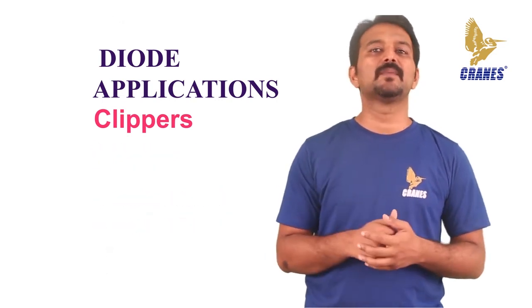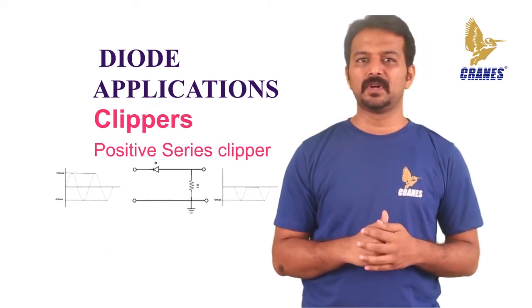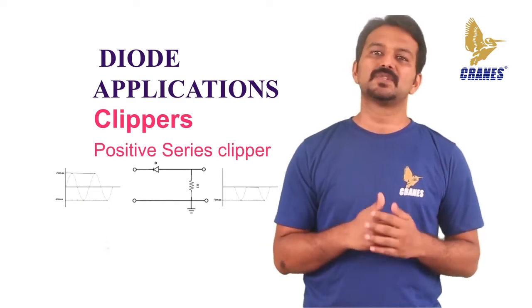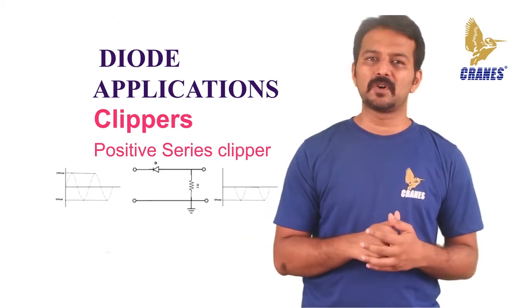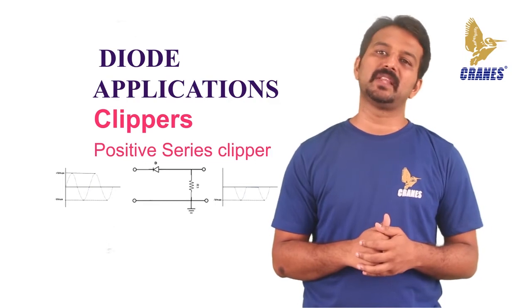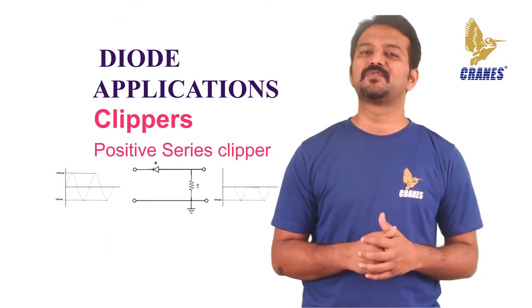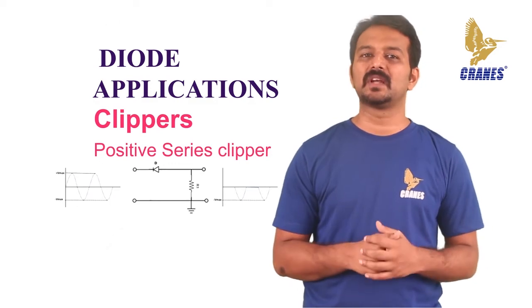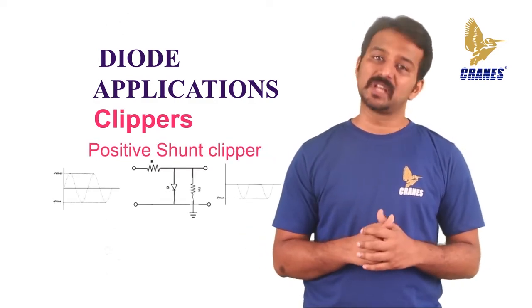So let's look at the positive series clipper. During the positive half cycle of the input, the diode is reverse biased. So the voltage at the output is 0. Hence, the positive half cycle is clipped off at the output. During the negative half cycle of the input, the diode is forward biased and the negative half cycle appears across the output.